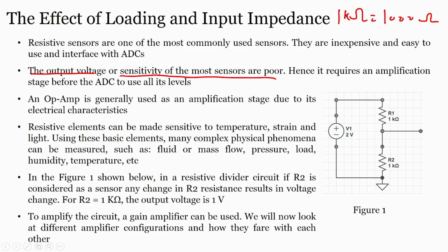Now, if the change in the resistance is 50 ohms, when we apply pressure or force, the new value, base resistance BR minus delta R, is 950. That means the difference is only 50 ohms. This will determine the sensitivity, how sensitive it is. The more change from 1000 to the new value, the better the sensor is, alright.